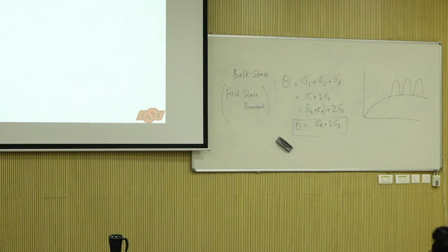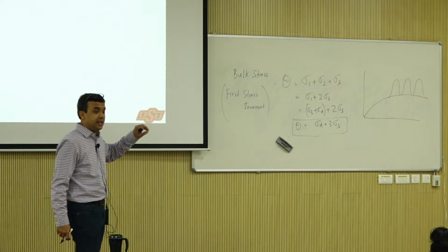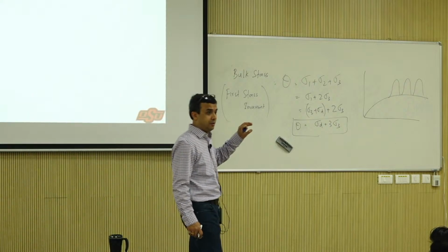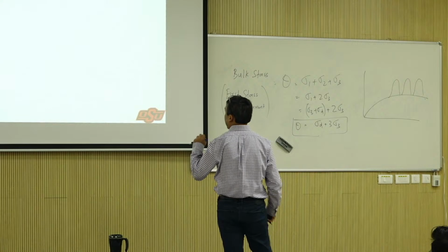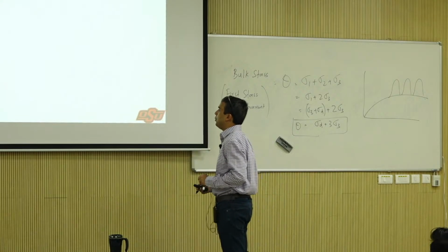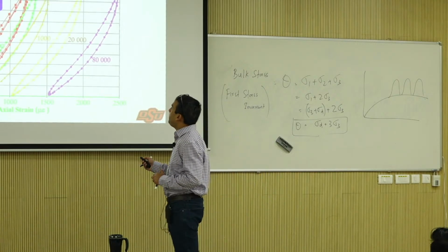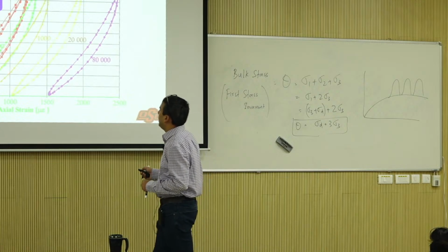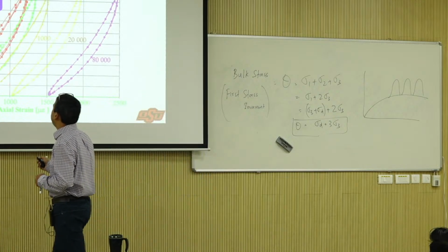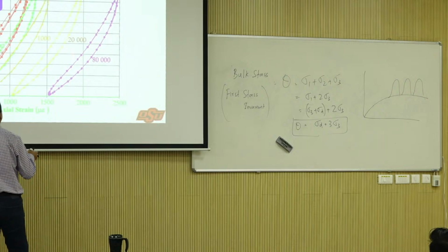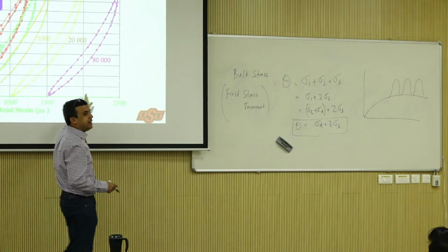Materials, we're going to talk about cohesive soils and cohesionless or granular materials. They are different. They behave differently under repeated load. Okay? And we're going to talk about testing approach. This is typical data that you would obtain, deviator stress versus axial strain, for a granular material.